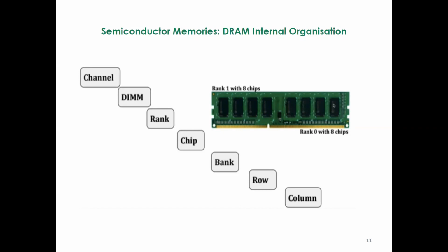the smallest storage unit, comprising columns and rows, which depending on the size of the DRAM chip you want to build or you are working with, you can have those rows and columns making up a bank, and then those multiple banks being put into one chip to provide a certain capacity. Then the multiple chips create a rank.